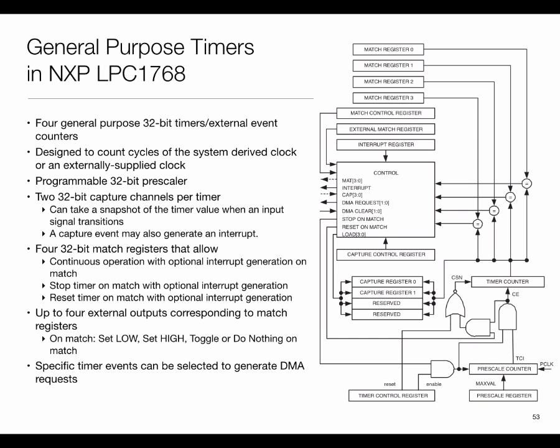So one way is that you can literally have an n-bit number. You output that, have a digital to analog conversion, feed it out, but then you need lots of pins for it. So what pulse width modulated waveforms do is they generate a square wave whose duty cycle is the analog value I seek to convey.